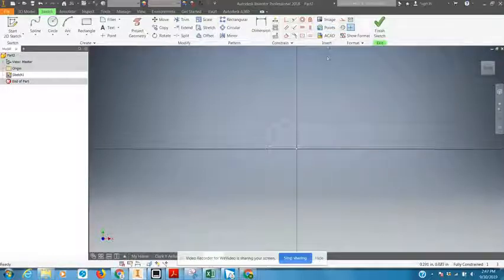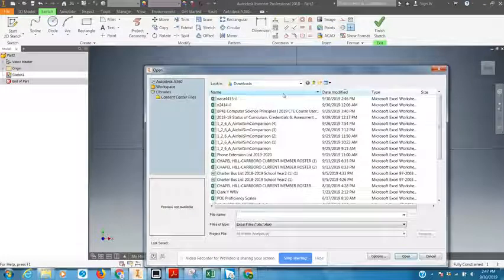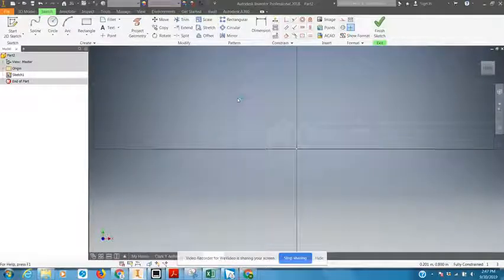So I'm going to come over here to insert points. I'm going to select that. And in downloads, here's our file. It's the NACA 4415 that we just created. I'm going to go ahead and double click on that, and it imported all those points.